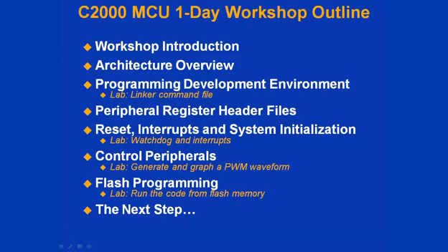Next, we will dive into the device and learn about reset, interrupts, and system initialization. In this lab exercise, we will use the watchdog to generate a reset and interrupt, reinforcing what we have just learned. Then, we will cover the control peripherals, which includes the ADC, EPWM, eCapture, and EQEP. In this lab exercise, we will generate a PWM waveform, then feed it into the ADC and graph it using Code Composer Studio. Additionally, we will learn about the real-time mode emulation features.